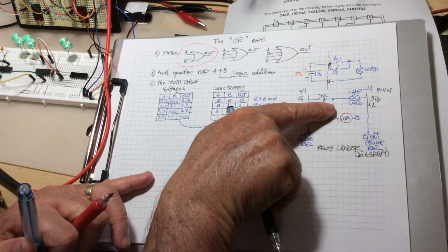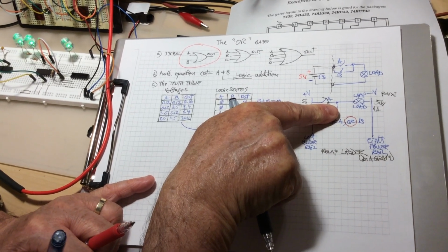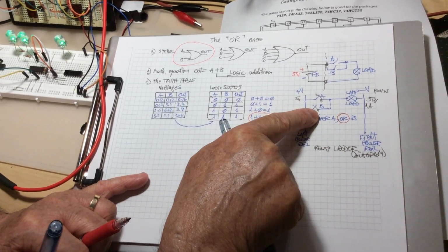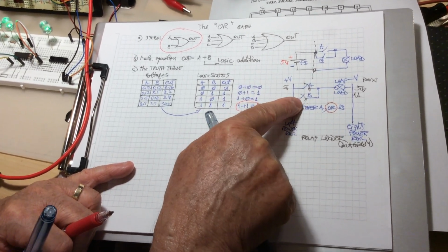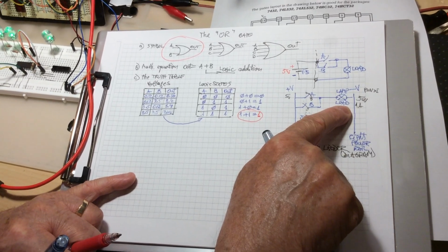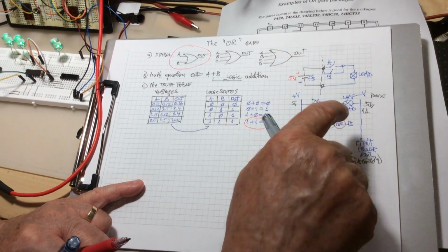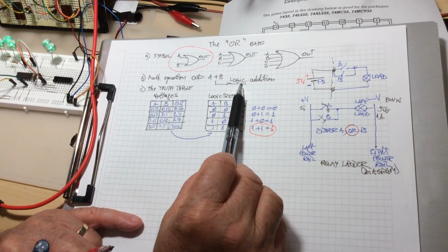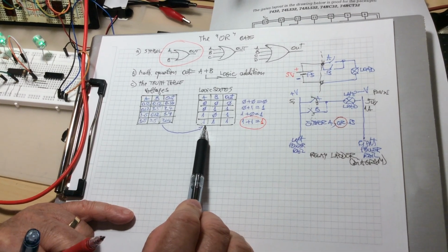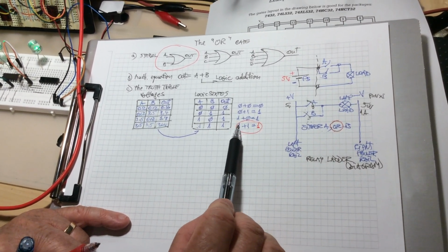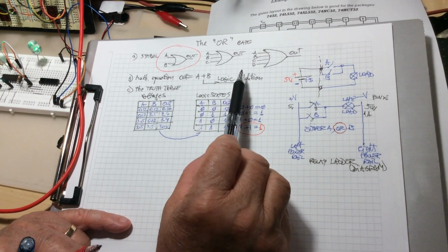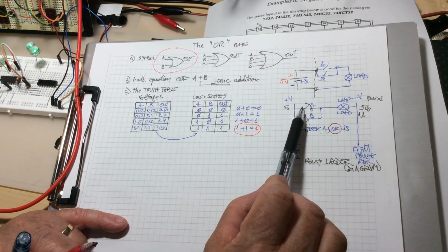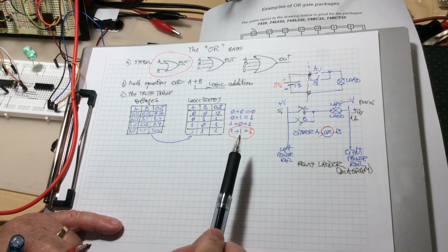The difference is if you only have one switch on, if the switch fails, there is no power over the load. If you have two switches, maybe this diagram is a bit more reliable, but it doesn't change the fact that the amount of power going over the load is the same. And the meaning for you, when you see that logic operation called logic addition, which is written on the paper with the same mathematical symbol like the arithmetical addition, 1 plus 1 is 1. In your mind, you have to have two switches in parallel.